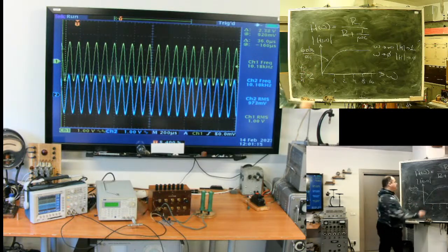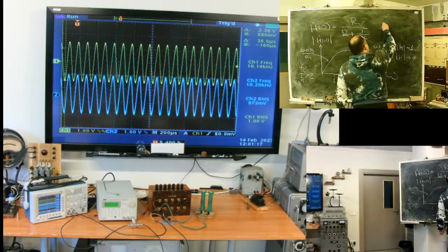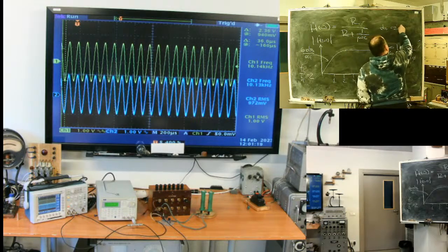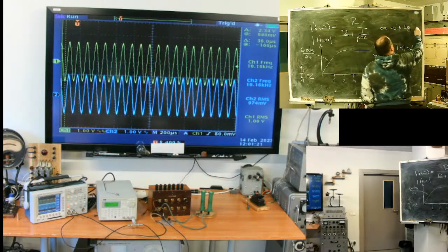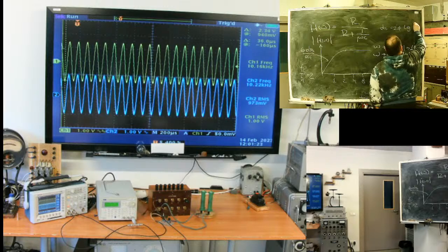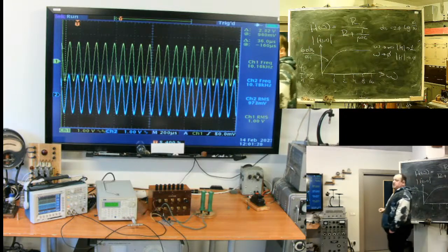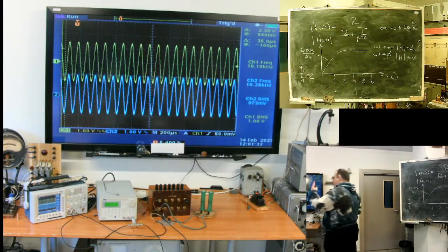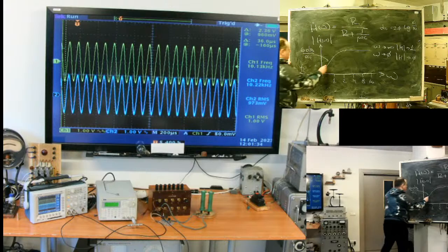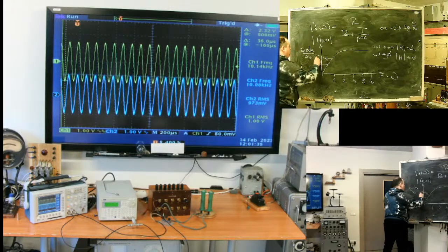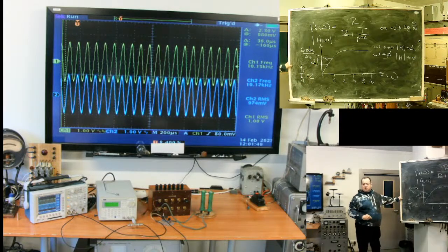So a step of 1 octave means on each unit of scale, frequency doubles. Decibel. Scale in decibels is 20 decimal logarithms of, let's say, some x1. 6 decibel also means twice. This means that between this point, the signal doubles.